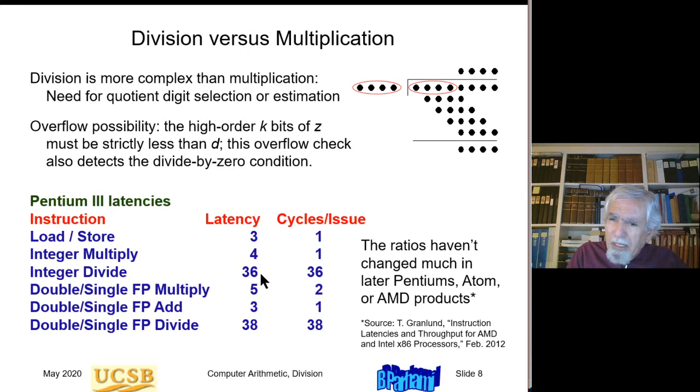So just remember that add and multiplications in modern processors are roughly of the same order of complexity. Nowadays we can do add, multiply, whether it's floating point or fixed point, in 1 cycle. Okay, so things have improved since Pentium 3. So add and multiply take 1 cycle in the fastest microprocessors. If you're talking about the lower speed microprocessors, maybe add takes 1 cycle and multiply takes 2 or 3 cycles. Okay, still, it's a fairly small number of cycles.